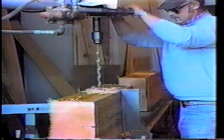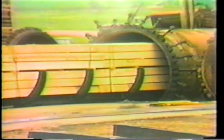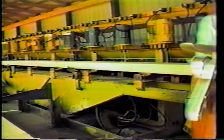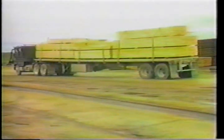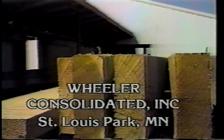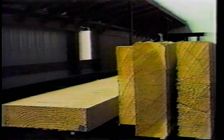We have looked at general concepts and uses for timber bridges, as well as talked about the design of timber bridges. The key to success begins with the treatment of the timber itself. So let's start there, the arrival of the raw wood. While many types of timber have been used for bridge construction, this firm, Wheeler Consolidated, St. Louis Park, Minnesota, prefers Western Douglas fir.